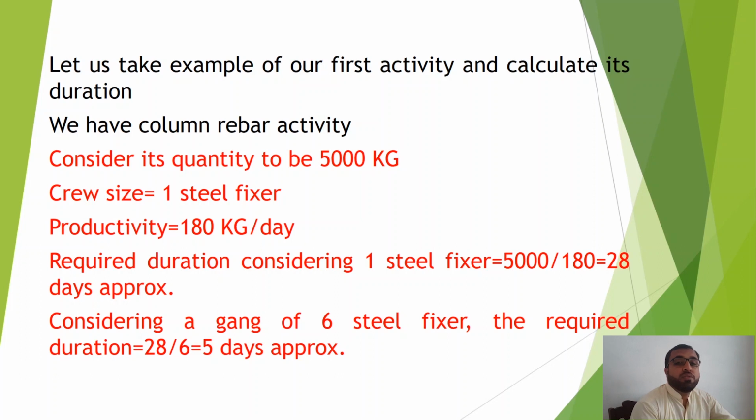So this is how we are going to calculate the durations. To calculate the durations, we must have the quantities available for all the activities, and we must have the productivity norms available with us. These productivity norms will vary from area to area, and from country to country. But for some productivity norms we have a rule of thumb, so we can use those to calculate the durations.